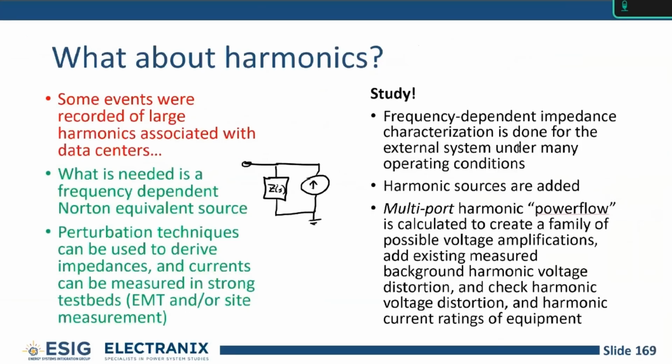So it's not a trivial problem to calculate what those harmonics are. You can do it in basically two ways. You can have an extremely detailed EMT model, like the one we talked about yesterday, but now with the switching included, for every device within the load. That's going to be a challenge right now for you to get, although it is coming. We'll talk about models in a bit.